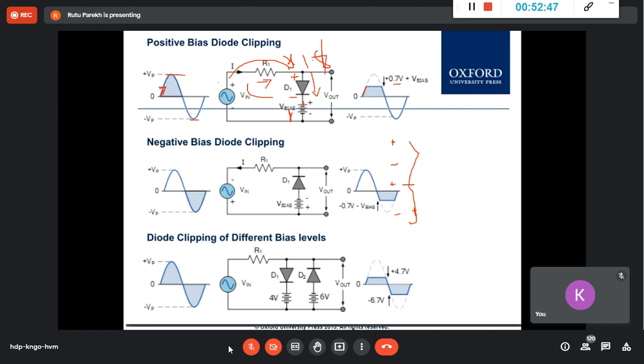And then when it is 1.8, this is forward bias. If it is 2 volt, 3 volt, this is forward bias. And whatever the voltage, 5 volt, 3 volt, 2 volt, the drop across the diode is 0.7, and then plus this 1, so that is 1.7. So whatever the input you are changing, your output is still 1.7 if V bias is 1 volt.